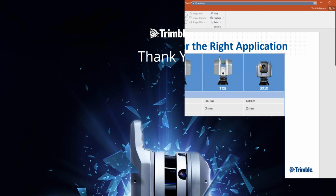Excellent. And finally, is the scanner self-leveling, which I think you covered. If you just want to run through that again, Ted. The scanner is self-leveling, yes. As I said, as long as it is within plus or minus 5 degrees, we will level it to better than 3 arc seconds. The scanner can be tilted all the way up to 45 degrees, and we will still level it. The only thing is that it won't be within 3 arc seconds. So even at 45 degrees, we actually can level it.